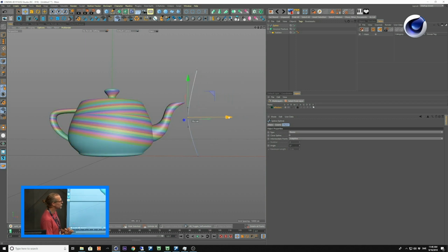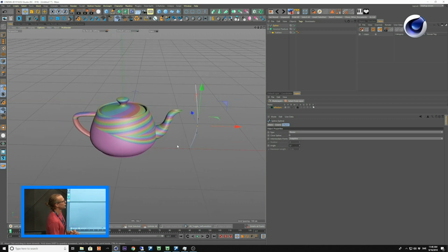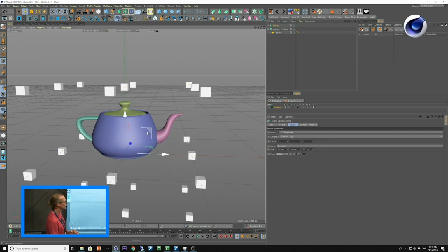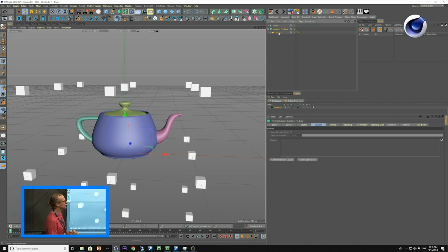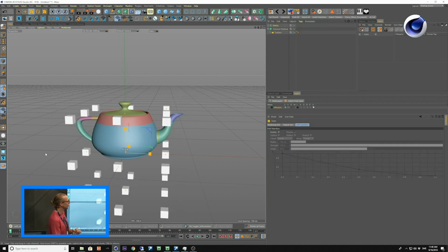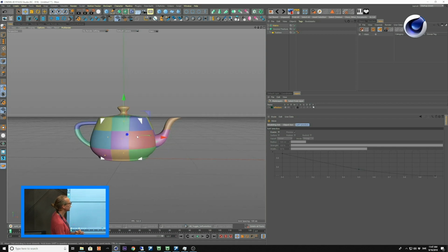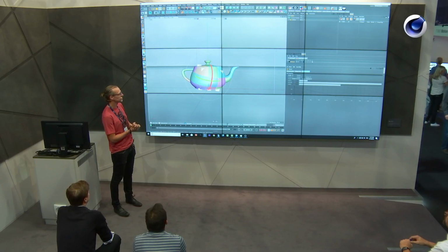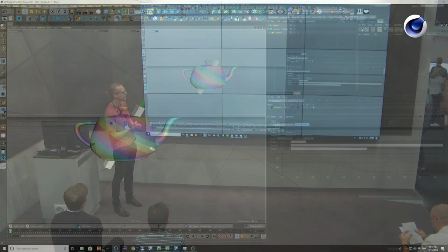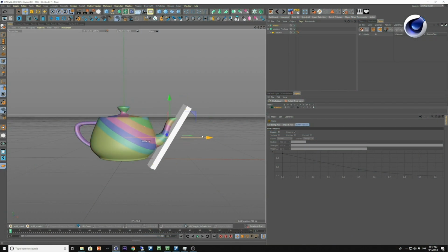Another way of doing cuts on a mesh is with the matrix object. So you can add a matrix object and use that instead of a spline, which is also very handy. So now I've added a matrix object, and I put that into the source object, and now the matrix object is controlling where I want my cuts to be. And I'm not restricted to just a line of rows, but can do volume cutting in this way. If I want the slice look, I'll just have one row and increase the numbers in Y. And I have a live cutter this way.